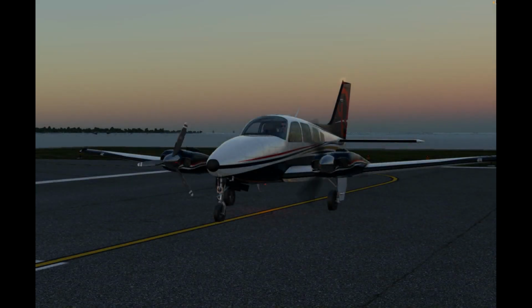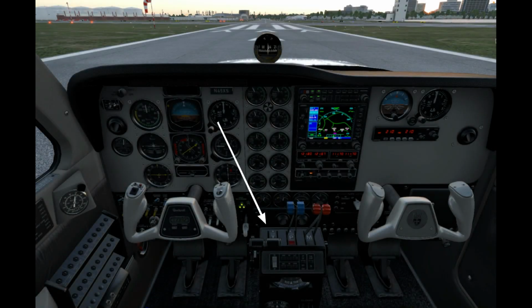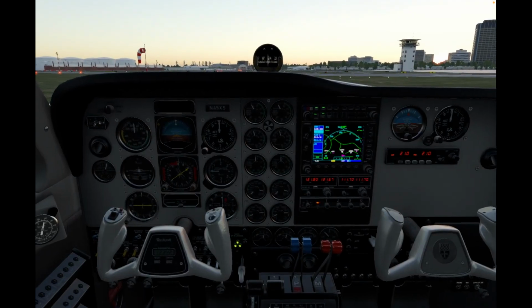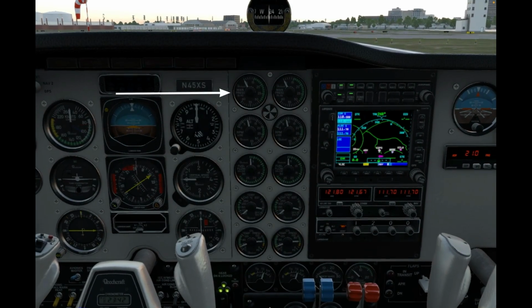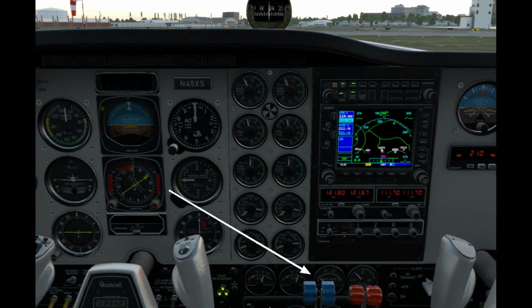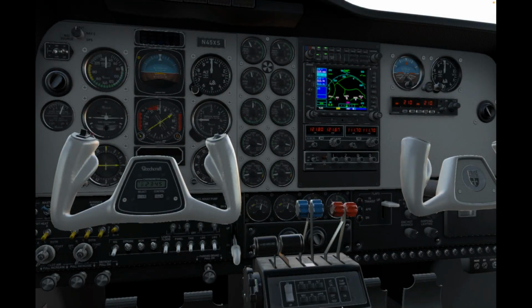A constant speed propeller is a controllable pitch propeller with pitch that is automatically varied in flight by a governor, maintaining constant RPM despite varying air loads. Constant speed propeller airplanes have both throttle and propeller controls. The throttle controls power output, which is registered in the manifold pressure gauge. The propeller control regulates engine revolutions per minute, or RPM, which are registered on the tachometer. To avoid overstressing cylinders, excessively high manifold pressure should not be used with low RPM settings.